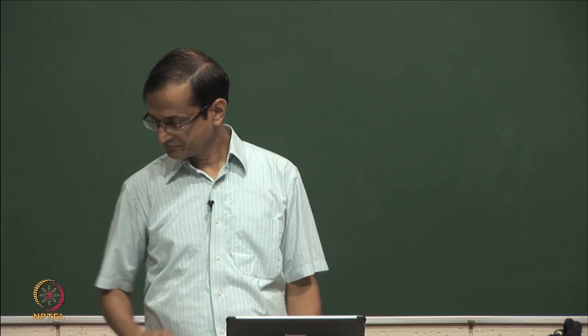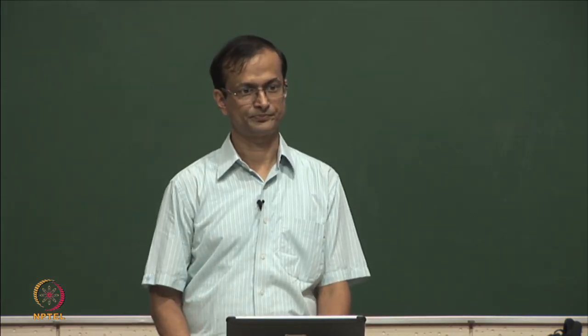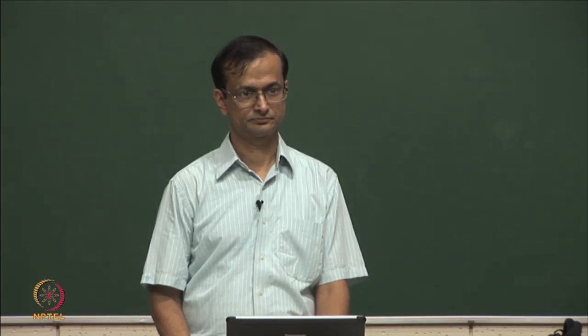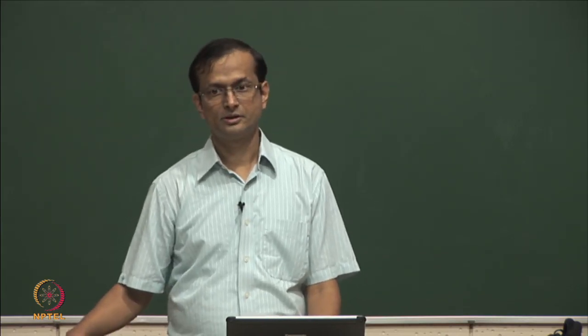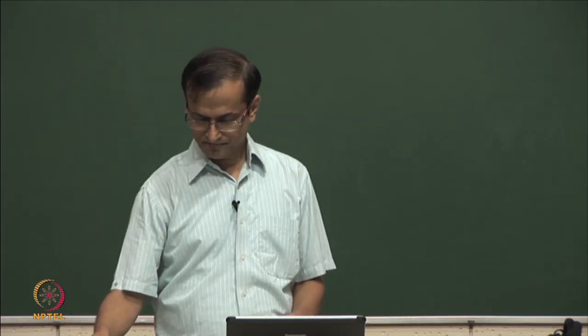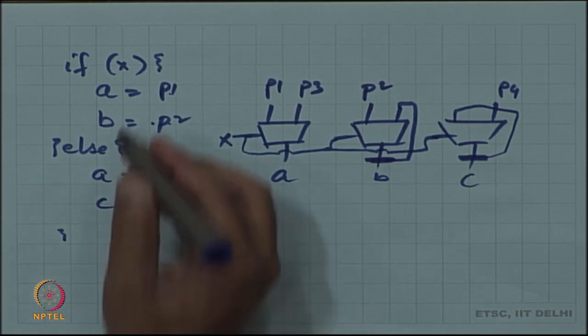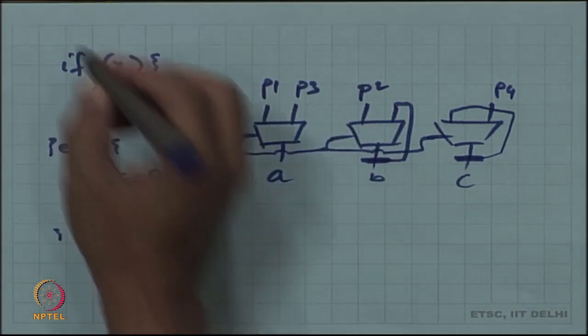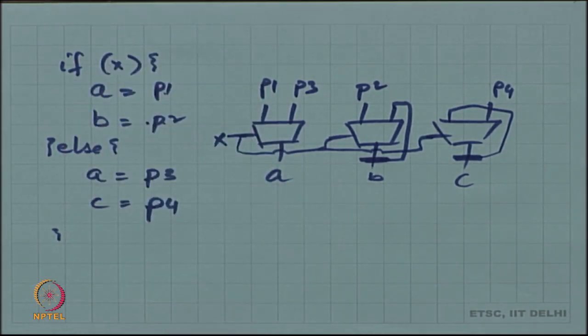Same happens if you have case statements in which, explicitly in the else block, if we explicitly declare in the if block we are saying A equal to, let's say, B, and in the else block we say A equal to A, then a latch will also be inferred. Yes. Else if you say A equal to A, that is fine, but the way to get around this, the way to still realize a combinational circuit from here, is of course to make sure that A is assigned something earlier, let us say A is initialized to a constant.